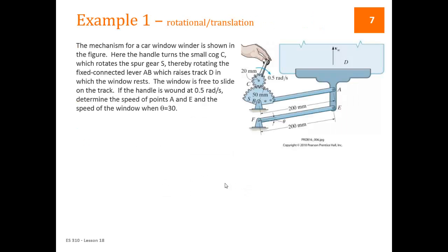So let's take an example of this. This is in old cars, right, that don't have power windows. This is how you would roll up and down the window. So you have a crank that the hand is on here, and you turn that crank, and as you turn that crank, you shift the angle of this S gear, this partial gear, which causes this beam to rotate upwards or downwards depending on which way you're turning, and this one's fixed to a fixed point, so this is going to move the same amount.